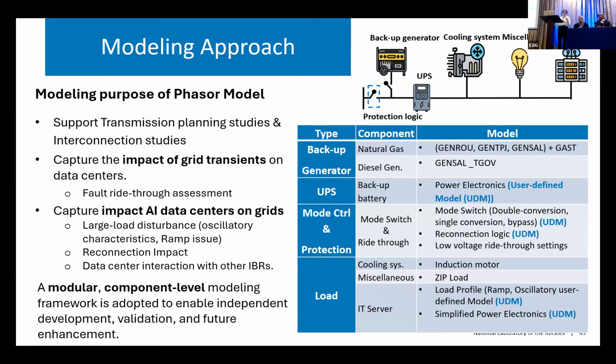Some of the dynamic phenomena beyond the phasor domain, like higher frequency, probably need to be captured with the EMT model. However, within 10 Hertz, there still could be some interactions. For example, there will be the inter-area oscillations. Originally, this is a synchronous generator issue. However, when you are thinking about the data center, if it can also enforce some oscillatory mode within that frequency, we should capture that in the Phasor model as well.